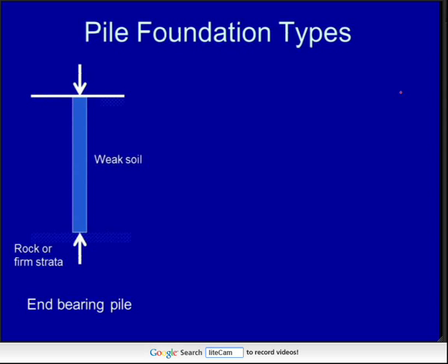If you're going to build this type of pile, why do you need to communicate that decision? Well, if you're boring a pile, you saw the picture of the boring. You saw these great clods of soil being thrown all over the place. And after boring, it's common to have quite a few of those sitting at the bottom of the hole. If you build a pile and you've got clods of soil at the bottom of the hole, then the first thing that will happen when you put a building on it is those clods of soil will compress and you'll get an increment of settlement not associated with the foundation, but merely associated with poor construction technique. So one of the things you need to do when you're looking at bored end-bearing piles is make sure, they call it mucking out, you have to clean the bottom of the hole thoroughly.